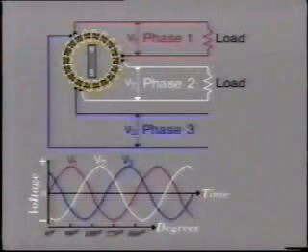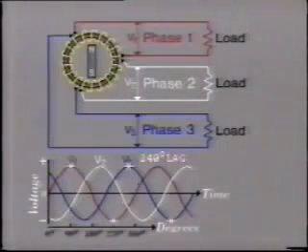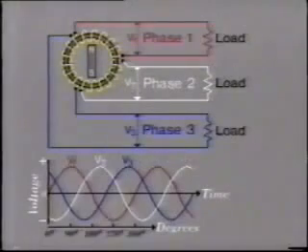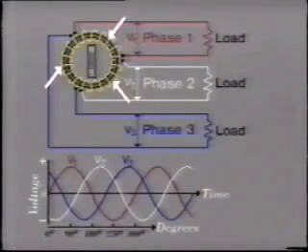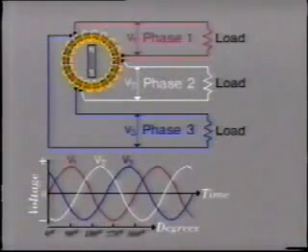In a similar fashion, we can utilize a third stator winding, which is placed yet another 120 degrees, that is 240 degrees from phase 1. This too can be connected to feed an individual single-phase load. And once again, its generation cycle is 240 degrees out of phase with phase number 1. So what we have in effect here are 3 independent windings supplying 3 independent loads, but each using a common iron core and rotating magnetic field. Almost 3 generators in one.